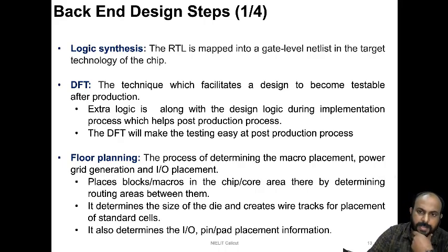So logic synthesis takes the design file RTL as one of its inputs. It also takes a user constraint file, which has the user given constraints of the design. Also it takes a lot of library inputs. So the output of logic synthesis is a combination of all these three inputs.